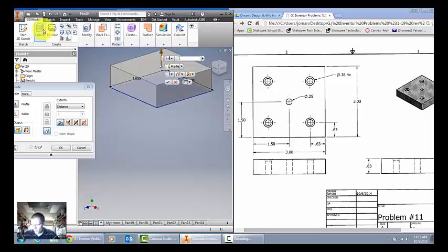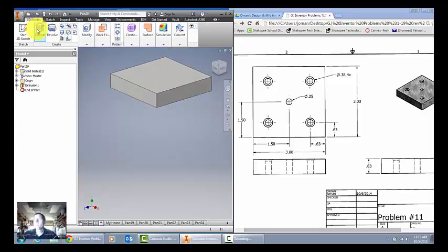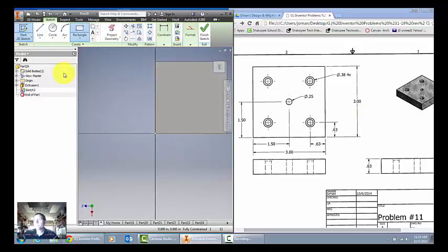Extruded 0.63. We're then going to sketch. I'm only going to sketch the center hole because it's different from the other 4 right there. So we'll do this one on its own sketch and then do the other 4 as a third sketch. So pick there.